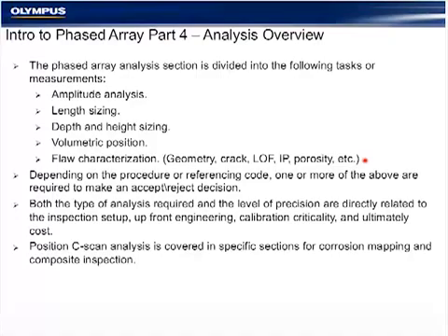We can have porosity and slag in most of our codes. We cannot have any cracks in any code that I'm aware of. So your ability to identify properly what type of flaw it is is essential. And all of our basic analysis tools in the software, our basic analysis strategies, can all be divided into these 5 groups and how we go about making a determination.